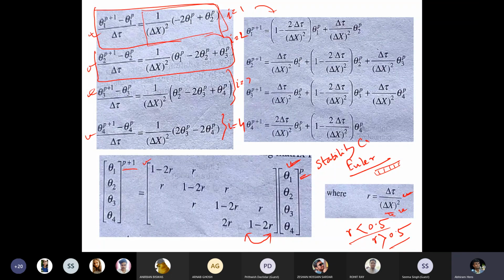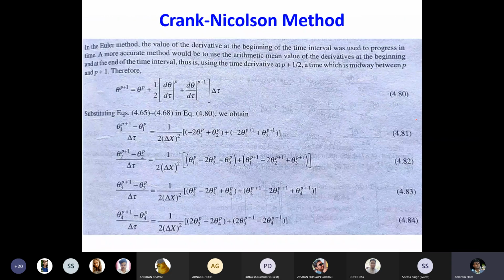Okay, this is just to simply understand the numerical stability concept. But there are many special types of stability criteria available, like the von Neumann stability criteria. Then there is the CFL stability criteria. These are different specific stability criteria proposed by numerical scientists. They have given that if you follow this, then your system will be more stable in nature. Okay, let me go to the next part. This I have explained, and the text part is written. If you read it later on, it will be clear why r should be less than or equal to 0.5.